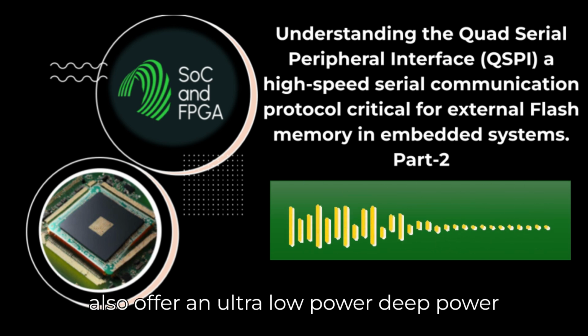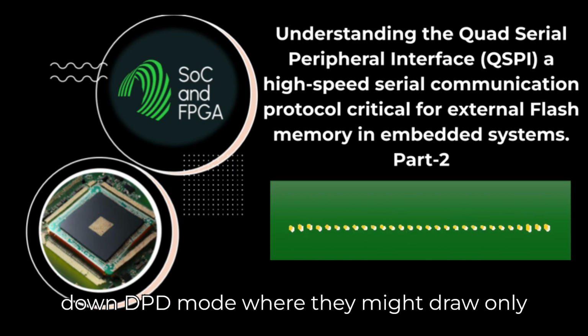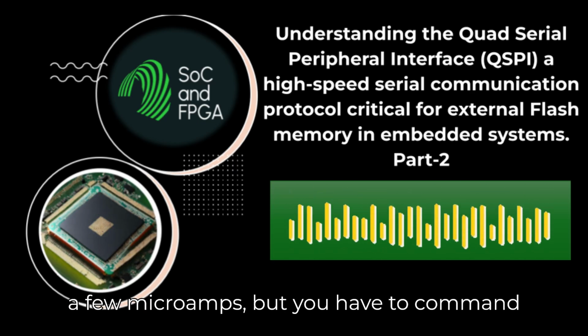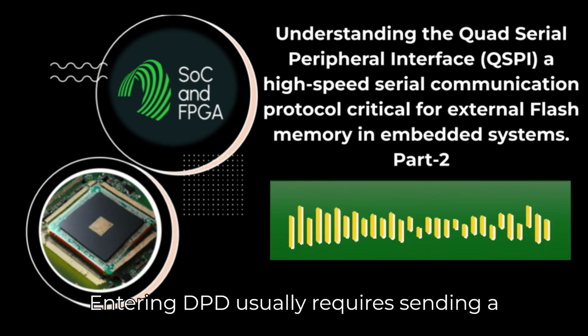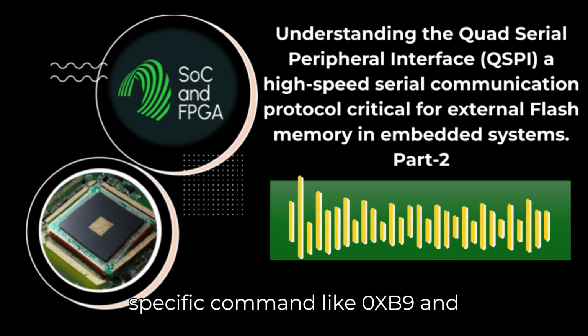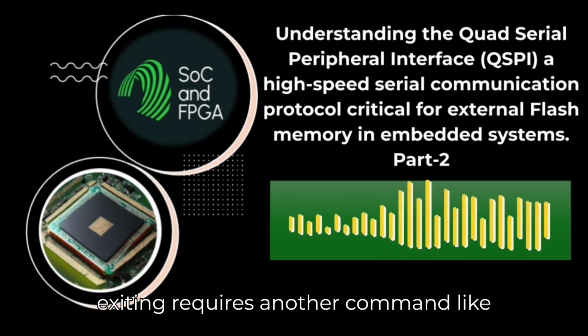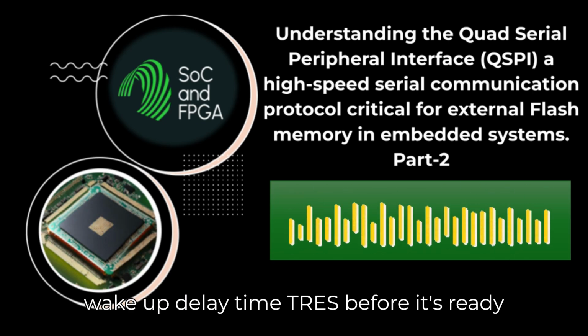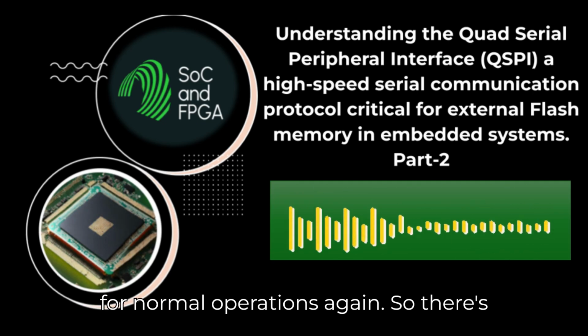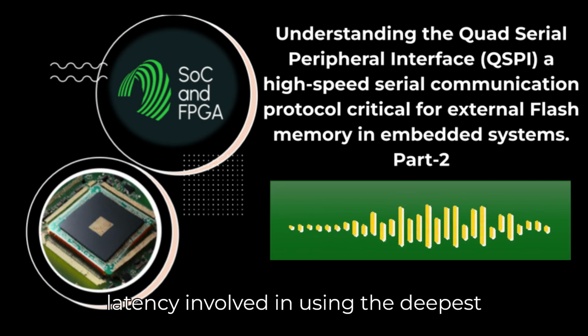And most also offer an ultra-low-power deep power down, DPD mode, where they might draw only a few microamps. But you have to command it into DPD mode and wake it up. Yes. Entering DPD usually requires sending a specific command, like 0xB9, and exiting requires another command, like 0xAB, release from deep power down, plus a wake-up delay time, tRES, before it's ready for normal operations again. So there's latency involved in using the deepest sleep mode.